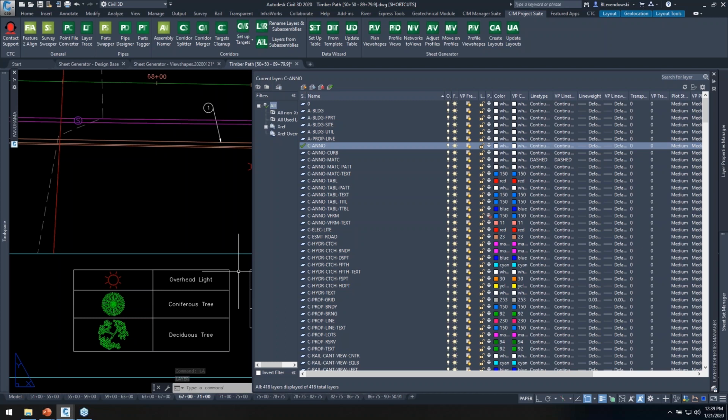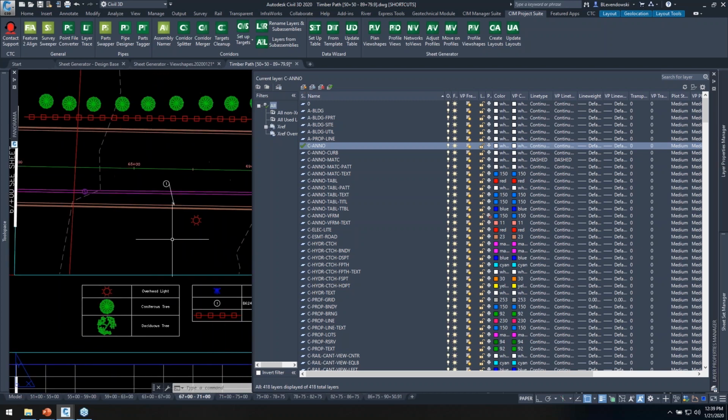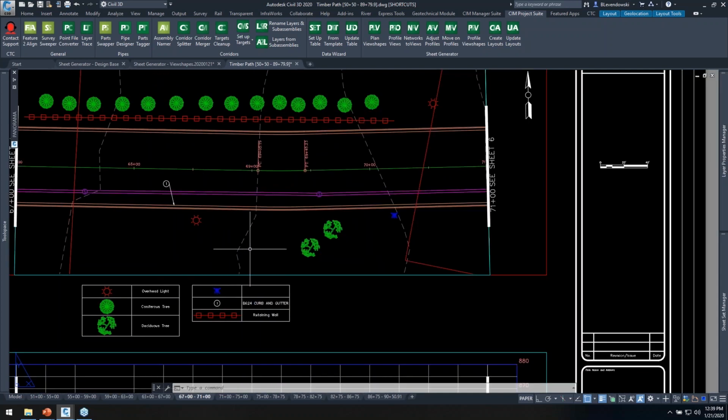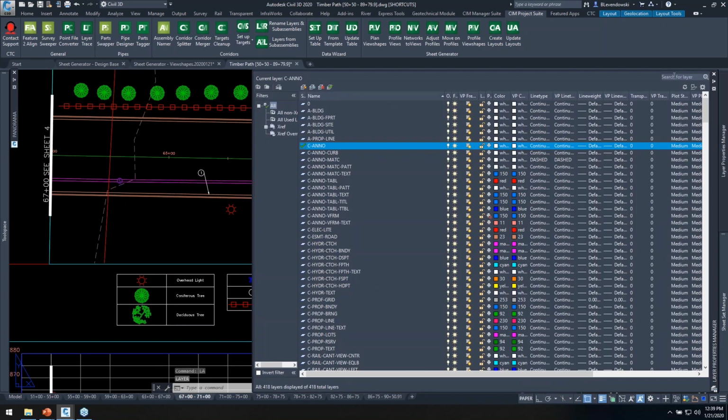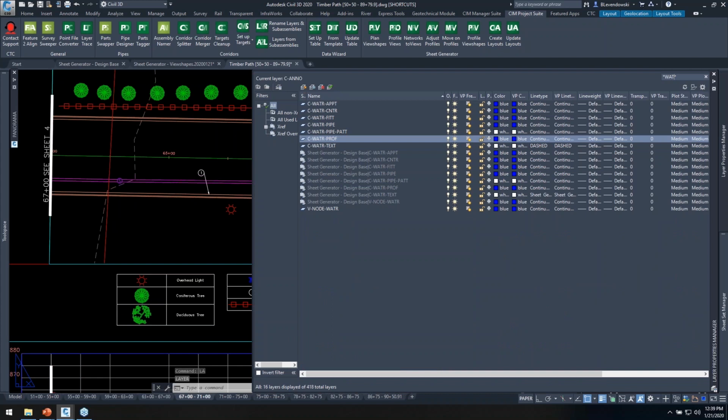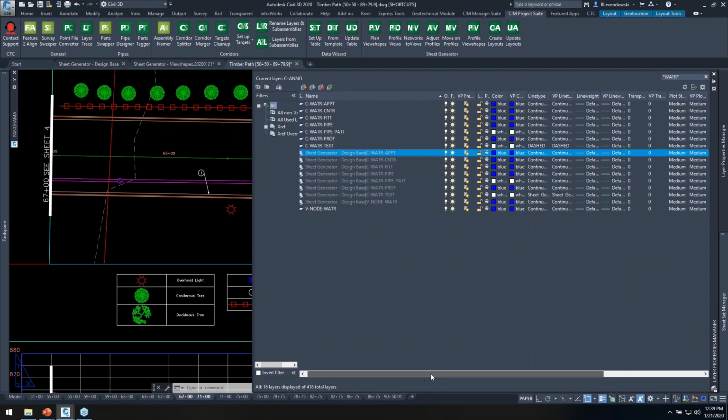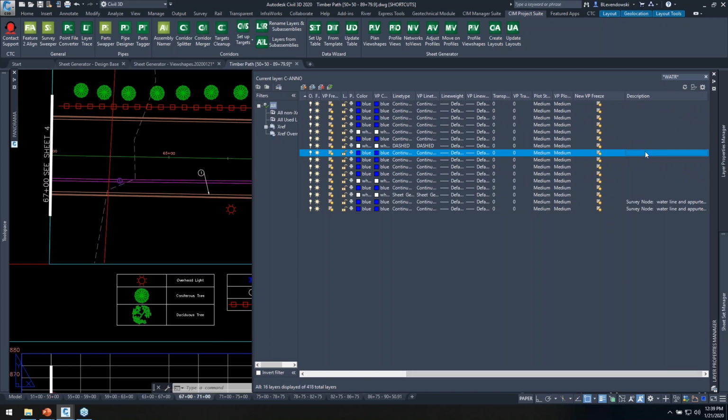These are dynamic tables, meaning if something changes in your drawing, they update in the same way. So perhaps you forgot to put the description in that layer that the hydrants are on, right? This happens to be in the base file, but I could just type it right in here and then you'll see what I mean.